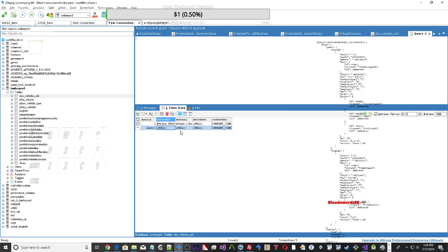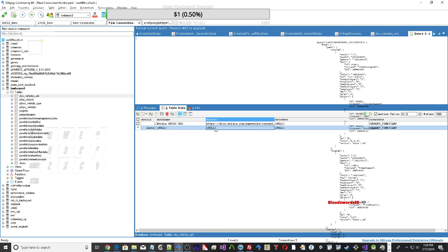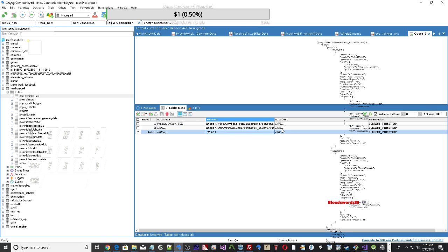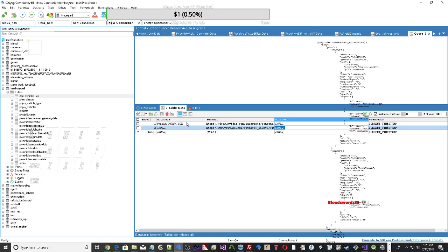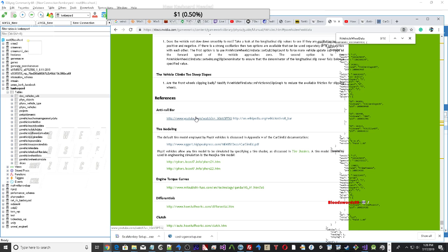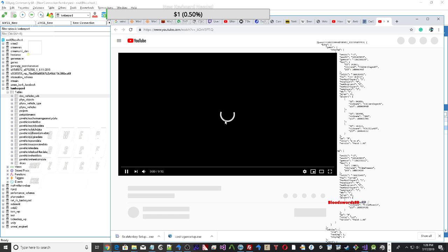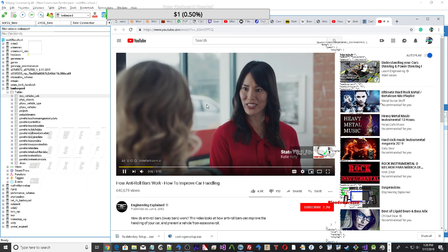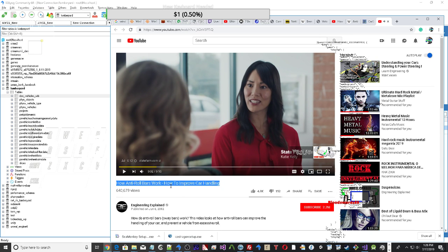These memory blocks are stored by each vehicle so that they may easily query the suspension raycast results in PxVehicleUpdates. As a consequence, this results array must persist until at least the end of PxVehicleUpdates and must have length at least as large as the total number of wheels in the vehicle's array.